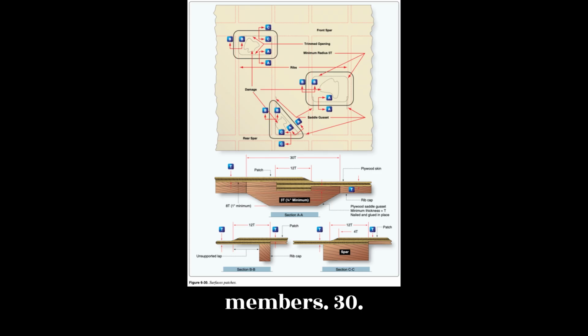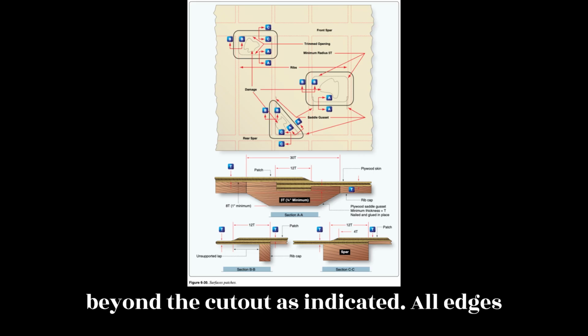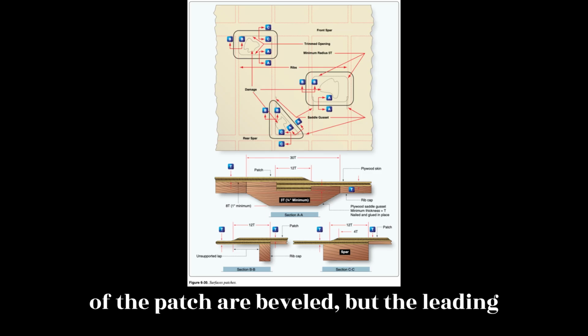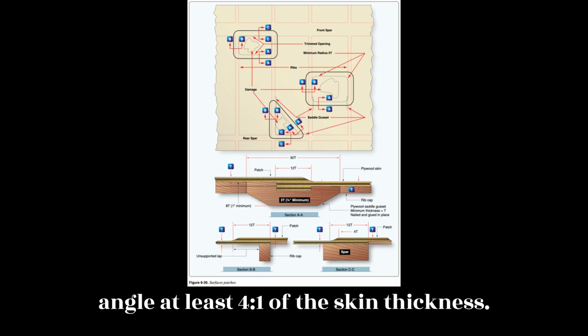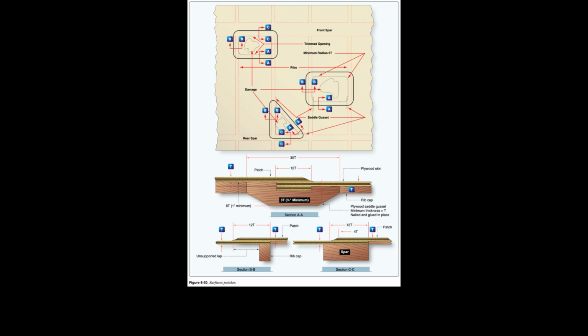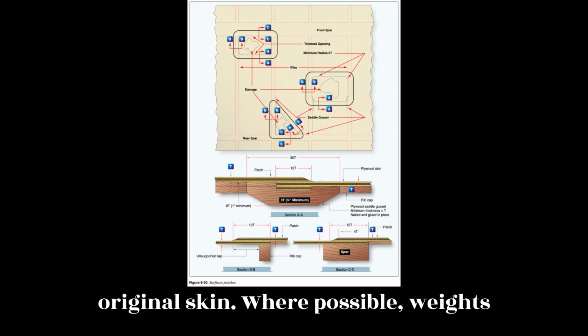framing members. Figure 6.30. The surface patch is sized to extend beyond the cutout as indicated. All edges of the patch are beveled, but the leading edge of the patch should be beveled at an angle at least 4:1 of the skin thickness. The face grain direction of the patch must be in the same direction of the original skin.